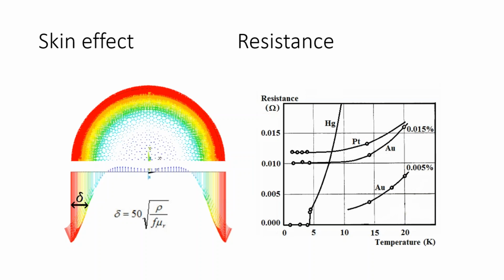But at any rate, before running the simulation, we can usually estimate, for a given frequency, conductivity of material and permeability of the material, this skin depth and then apply a finer mesh in this zone at which we expect to get most of the current, to get higher accuracy of our results.